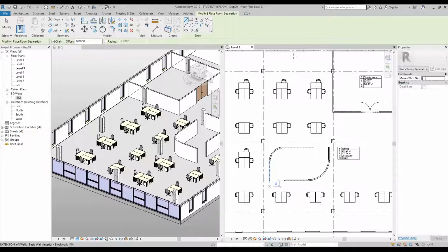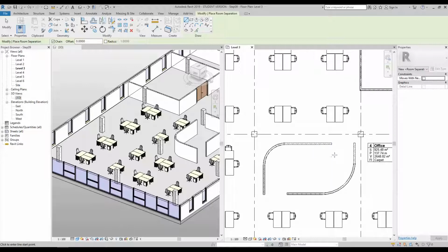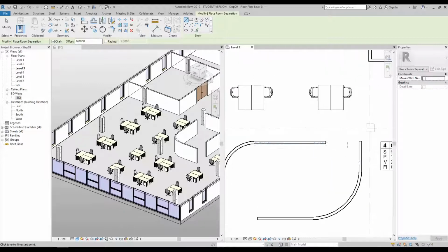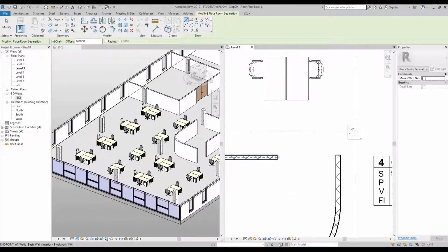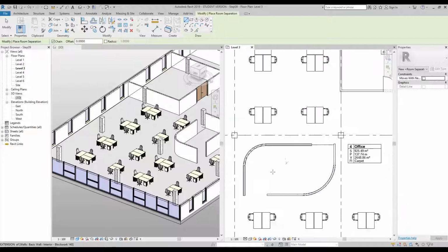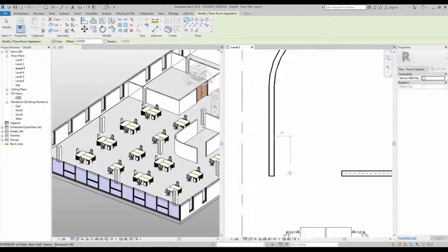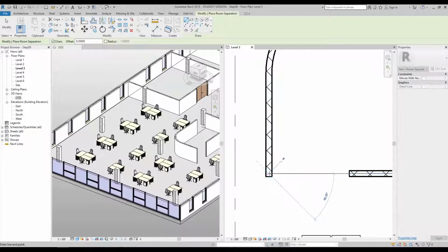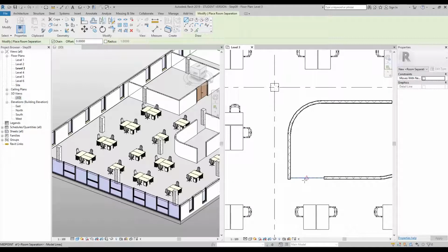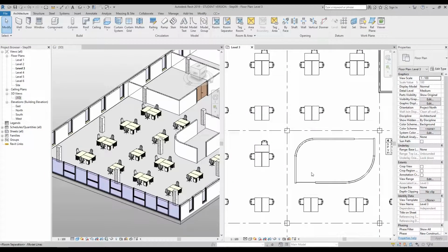Again, you are now in a sketch mode, so the user interface is turned green. I want you to zoom into the kitchen area, and with the single line tool up here, go to the opening, click once in the middle of the wall from the left hand side, and then go all the way to the right, and click again when you hit the other wall, and then press escape. Zoom out, go to the south side, click once on the opening wall, along to the right, click again, and then press escape to exit the command.